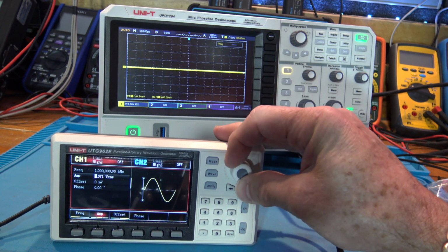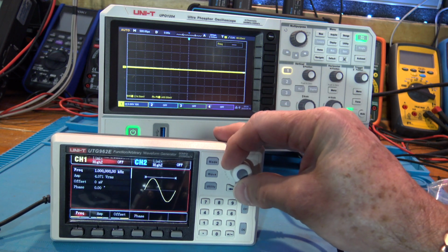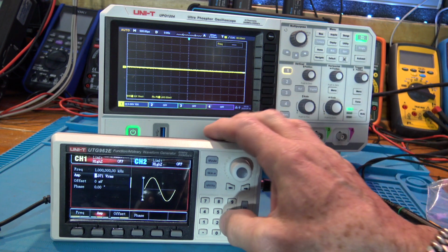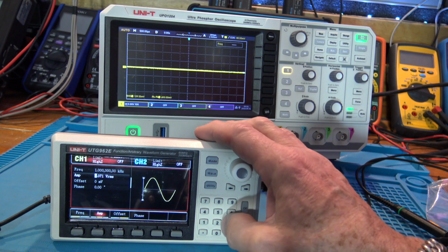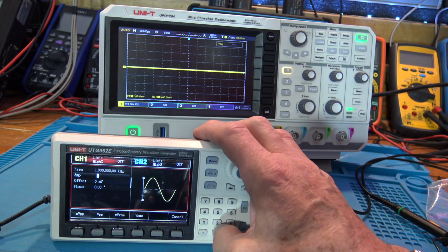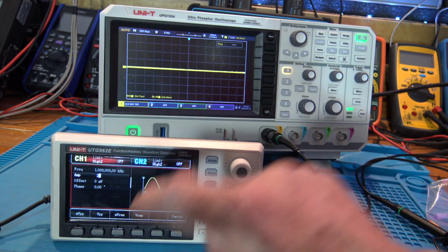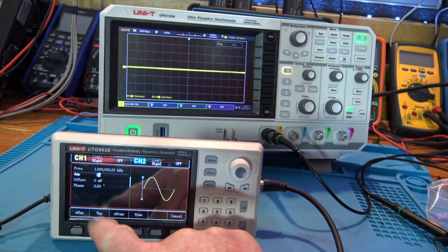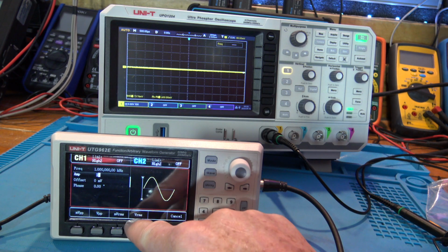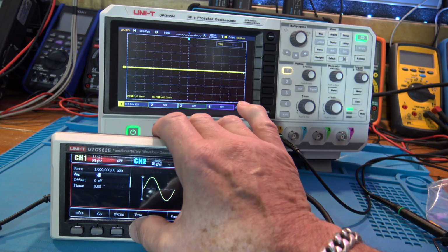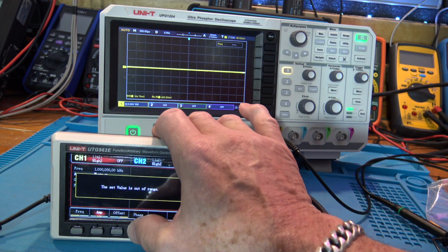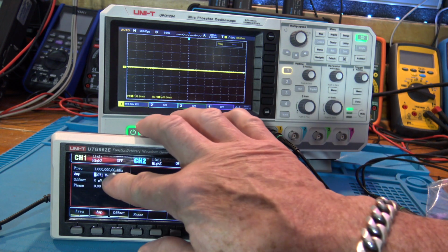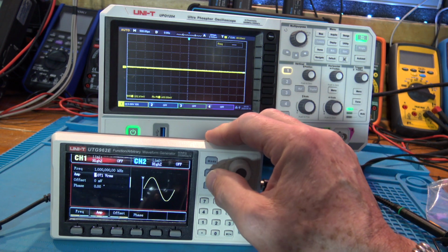So it looks like it's maxed out, 7 volts RMS, right? And then let's go back there. The other way, I can just start pushing in any number here. Let's say I'm going to go 20 volts peak voltage, or peak, okay? So we got millivolts peak, volts peak, millivolts RMS, and then our volts RMS. So let's just say I'm going to choose volts RMS. It's too high, right? So then I just push any button, and then it maxes it out, okay? So 7 volts RMS is the max.